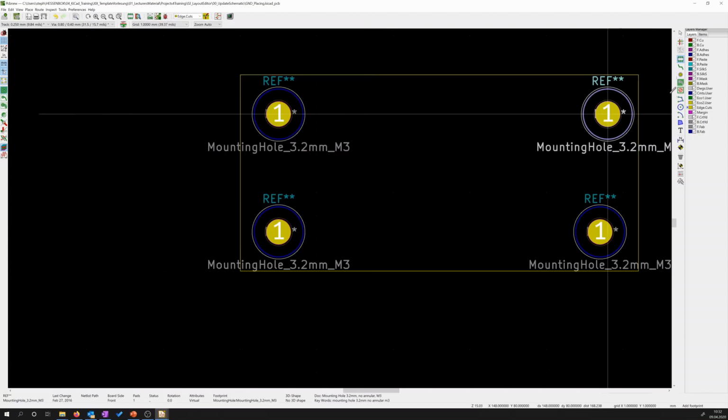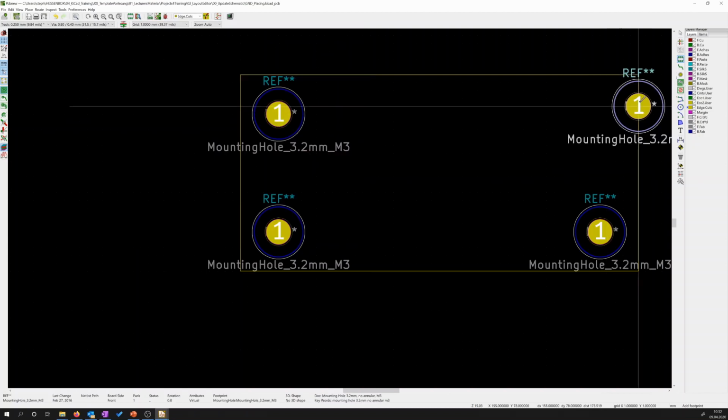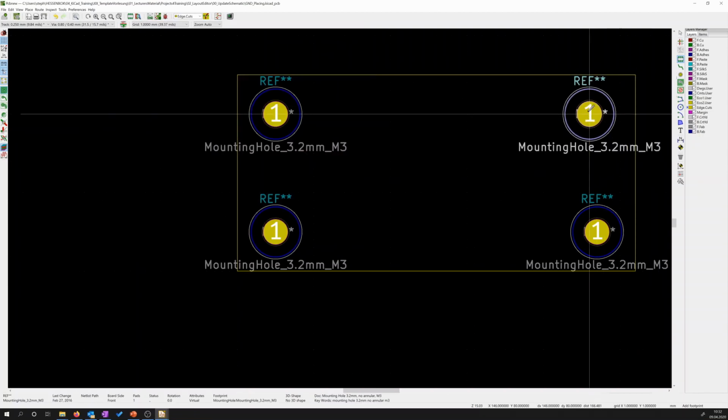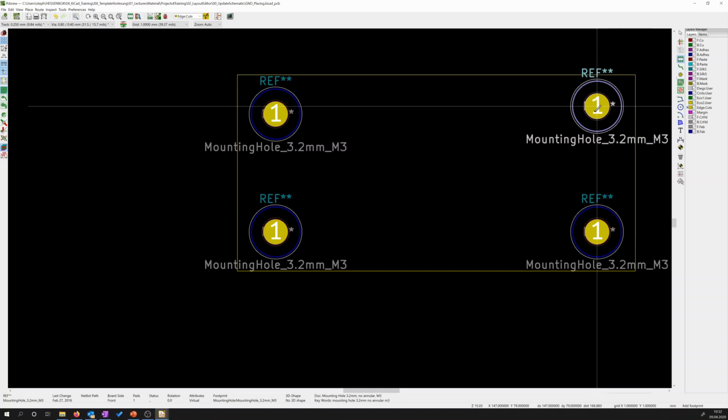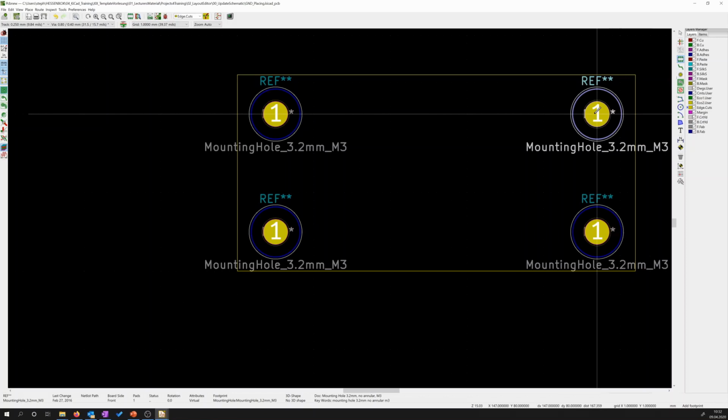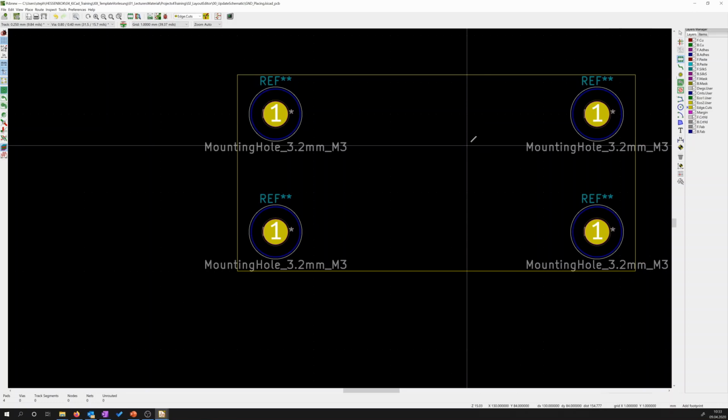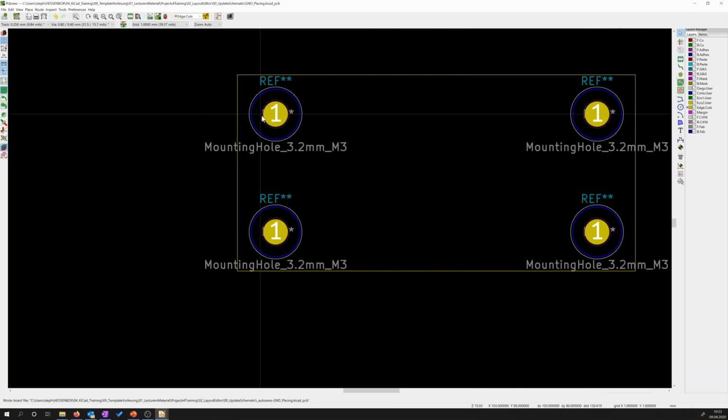Select, sorry. Now I move the mouse, you see. But now we know the position: 147, 80 is correct. And we left click and we deselect our tool by pressing the escape key. So that's how we positioned this for mounting holes, 5 millimeters space from the board outlines.